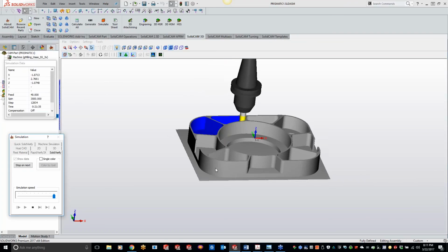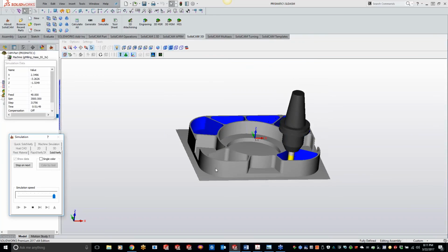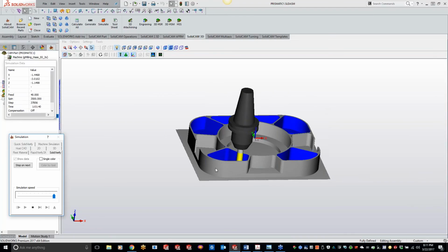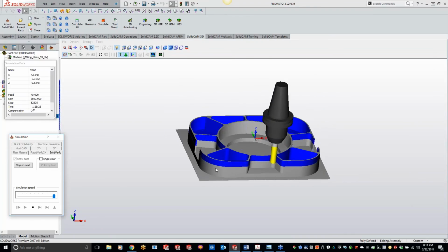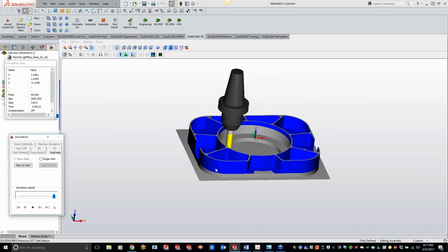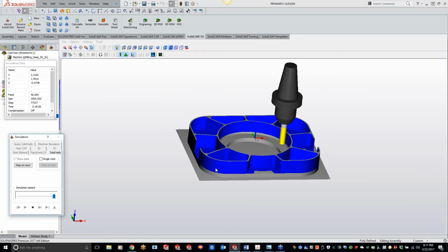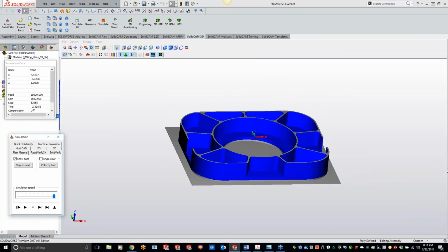So like I said, just doing the pockets there, doing the walls, does the floor. Like that too, Kevin, because the tool is staying down too. Yep. I mean, not a lot of rapids. And we're not jumping all over the part. Yep. And what it does, it tries to find the fastest tool path possible. So it is pretty smart technology, and we'll actually run into that with the 3D constant or 3D corner offset too. You'll see how it follows the technology.